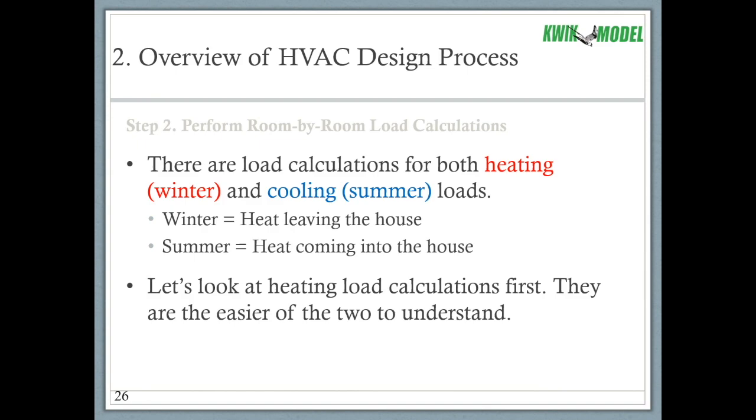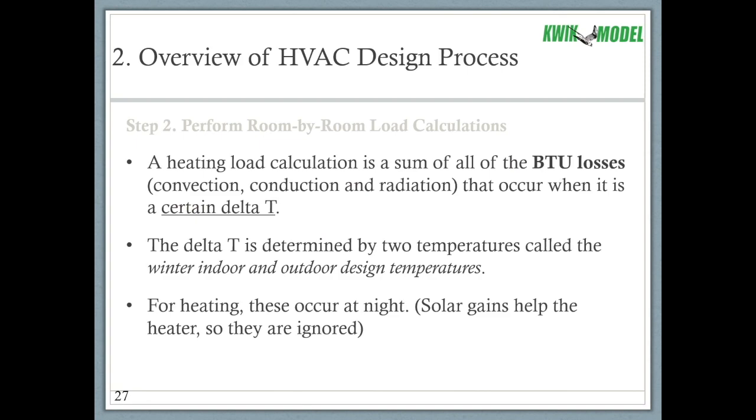Each one has two different temperatures, the indoor temperature and the outdoor temperature, that affect those load numbers, or that amount of heat transfer. Let's look at heating load calculations first. They're actually the easier of the two to understand. A heating load calculation is a sum of all the BTU losses. Those BTU losses can either be in the form of convection, which is heat transferred through moving air, or conduction, which is heat transferring through a solid object, or radiation, heat transferred by means of electromagnetic radiation.